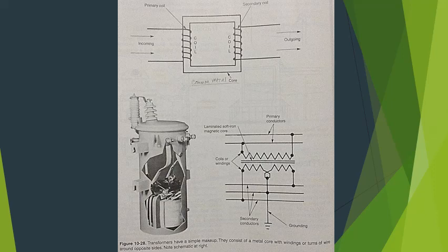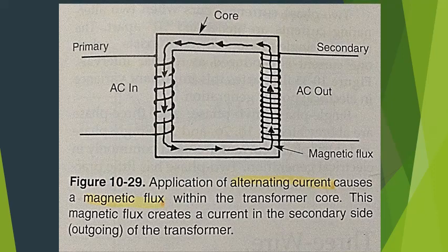This magnetic flux also moves through the coil, which is called the secondary. A current is created there too. Since the same magnetic flux exists throughout the core, the same voltage per wire is created. Therefore, any voltage difference is the direct result of the differences in the number of turns in the primary and the secondary windings.